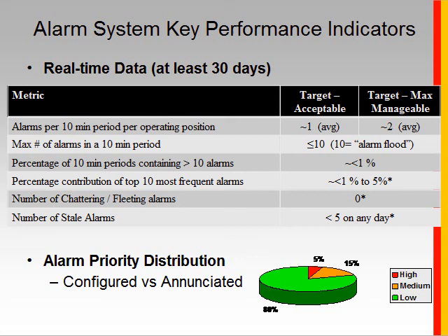You're also going to measure and look for which alarms are causing most of the traffic. If you find in an unmanaged system, and you typically find this, that there are 10 to 20 alarms that generate probably 80% of the alarm traffic, well, that's only going to get in the way of the operator doing his job, and it indicates a problem with the system, either going back to basic alarm design or a maintenance issue. So the ability to address those will clear up the operator's screen and make it much easier for them to perform the role that they need to do.